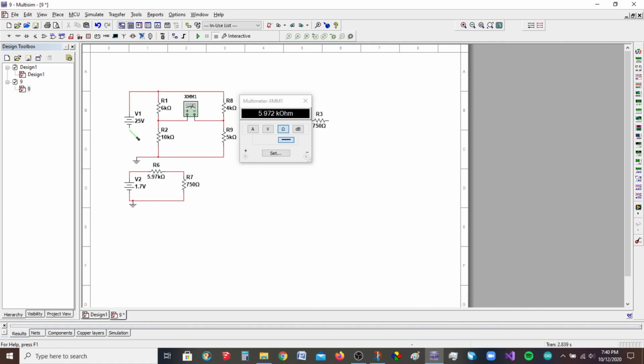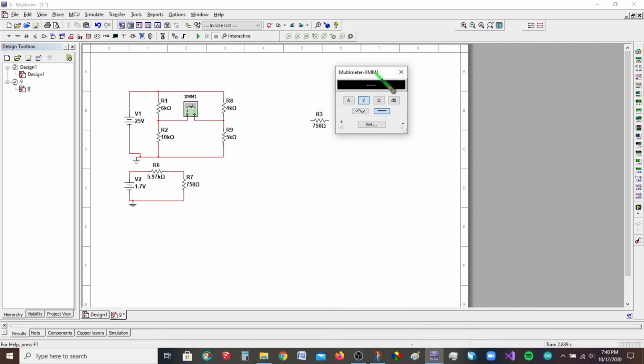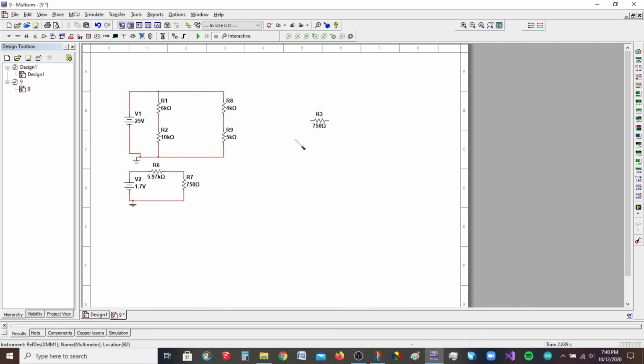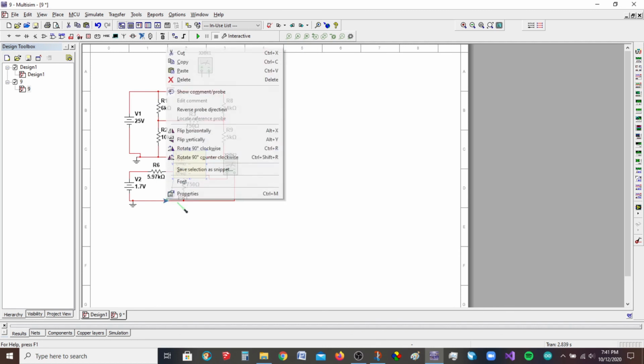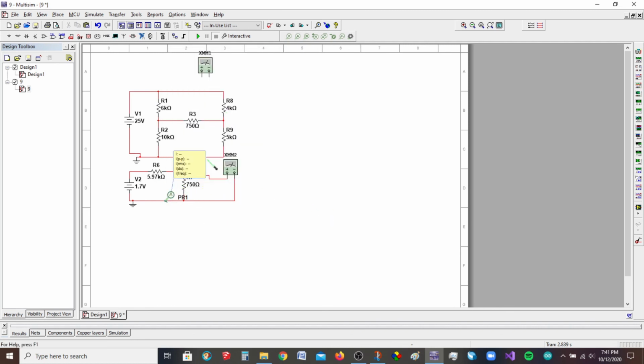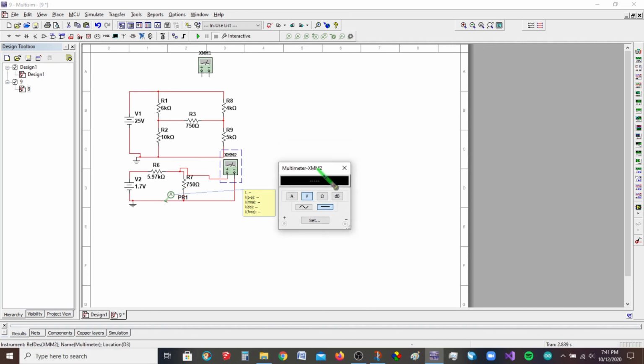And now we're going to look at the final characteristics of this resistor. Okay, so I'm going to put this resistor in here. Get rid of that. Put this in. I'm going to give myself enough room for the DMM and for the ammeter here. Okay, so now I want a DMM for each one. I'm going to measure the voltage here and measure the voltage here. This one will be the same. I guess I could have left all that stuff up, and then I'm going to put an ammeter here as well. I'm going to reverse that probe. Okay. So there's my bottom two measurements.